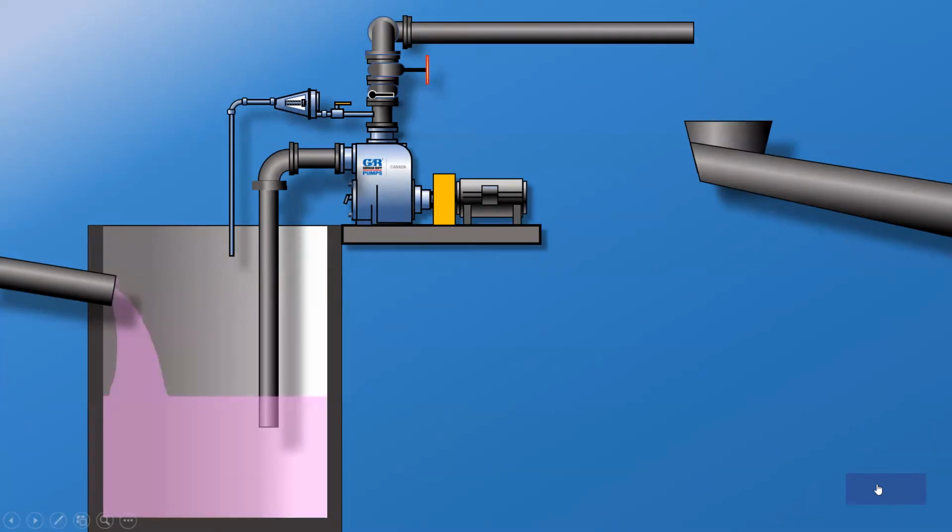And what we're getting is a stop-start inflow into, let's say, that treatment plant, which anyone who's looked at treatment plant design knows that treatment plants usually like a nice steady flow. So what we could do here is we could put some kind of a level sensor on the wet well itself. It could be a submersible transducer, or in this case, some kind of ultrasonic sensor, that's always measuring the level in the wet well.